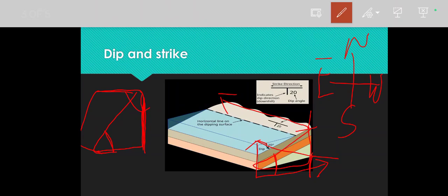And if you consider a line like this, then the dip will be something different. Your vertical plane will be like this, and this will be the apparent dip. Any line apart from the strike line and the dip measured in the vertical plane will be the apparent dip. Sometimes true dip and apparent dip are the same. It's not sometimes the same, it is always so when it is 0 degree.